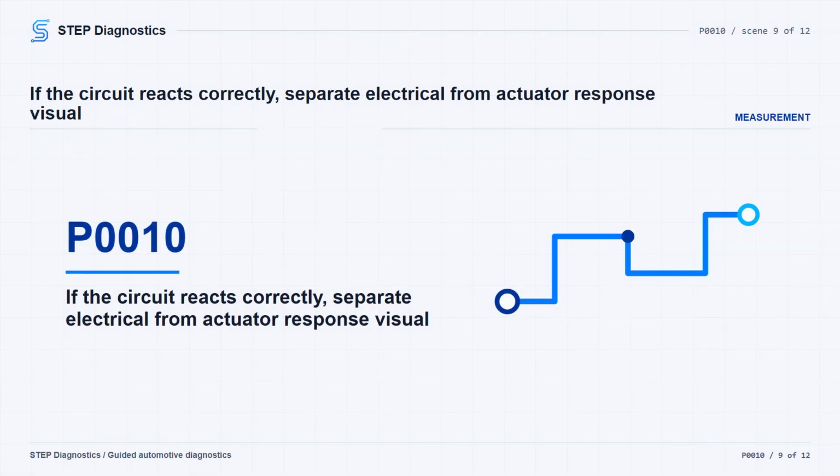If the forced low voltage check does show malfunction, then look at whether the cam actuator response code is also set. If that response code is set, turn the vehicle off and inspect the cam actuator related parts as a group: the solenoid valve, the actuator magnet, the solenoid valve assembly, and the mechanical camshaft actuator. If a condition is found there, replace the camshaft position actuator solenoid valve.